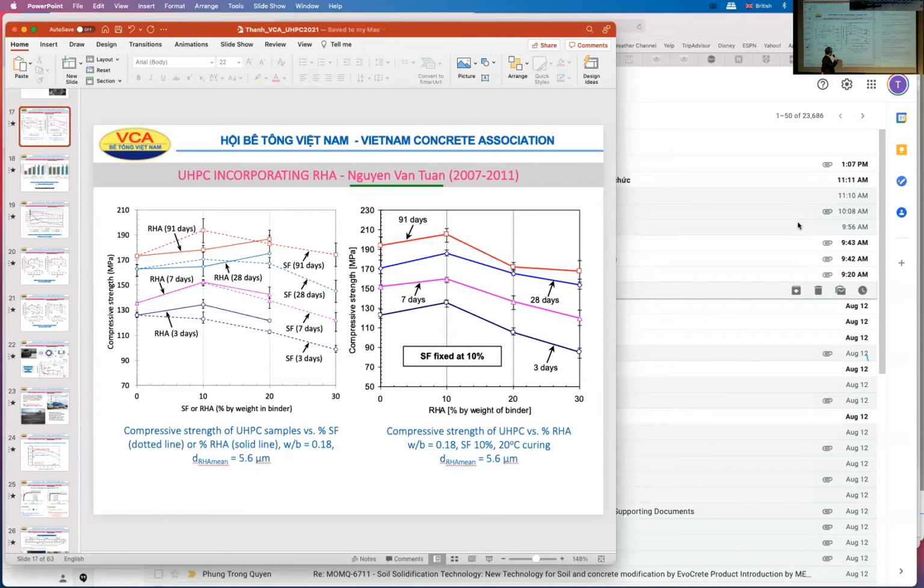The question from PPAT term is, what is the rheology in your study? Fly ash, slag, rice husk ash is bigger than silica fume. In general, replacement of silica fume by fly ash or slag or rice husk ash decreases the rheology. Maybe superplasticizer? Yeah, sure. We actually now have a very good superplasticizer, so we can sort this out. I think surely. The thing is that silica fume is the most expensive ingredient, so definitely our research team, and I think many research teams in the world, try to use as little silica fume as possible for UHPC. Okay, is that right? Yeah, UHPC, that's one of our strengths, flowability with the high range water reducer.